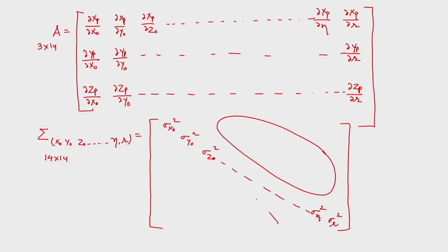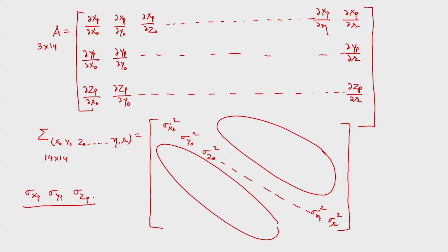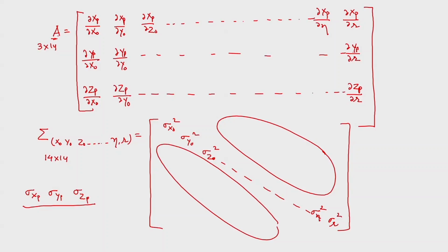And the rest of the elements are 0 here. So, now using the law of error propagation, I can find out the values of errors. That means we have determined sigma xp, sigma yp, sigma zp. You may find this process very complicated if you are doing it using manual calculation. So, use symbolic mathematics, use Microsoft Mathematics and try to write these equations there, then differentiate it, find out the A matrix, use symbolic multiplication and find out the complete expression of errors.